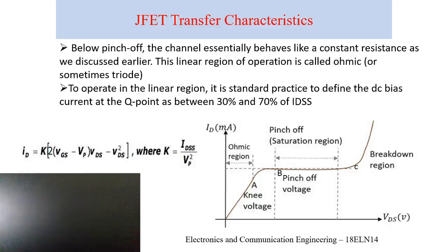The parameters IDSS and VP (VP is sometimes also called VT or VGS(off)) are generally given by the manufacturer. If they have been given by the manufacturer, then this makes things a little easier, as the Q point can be calculated.